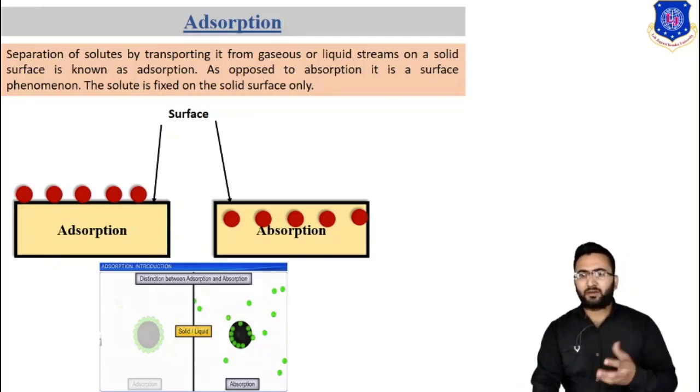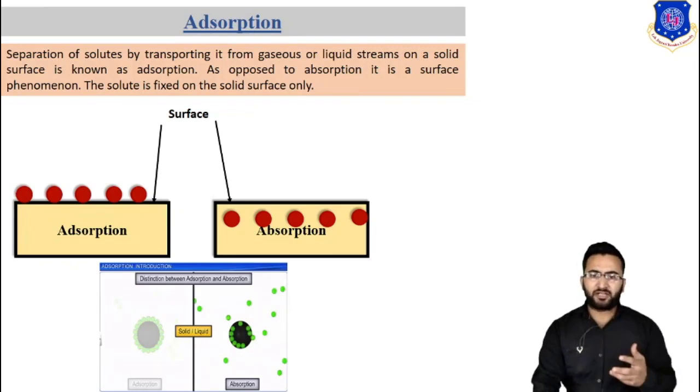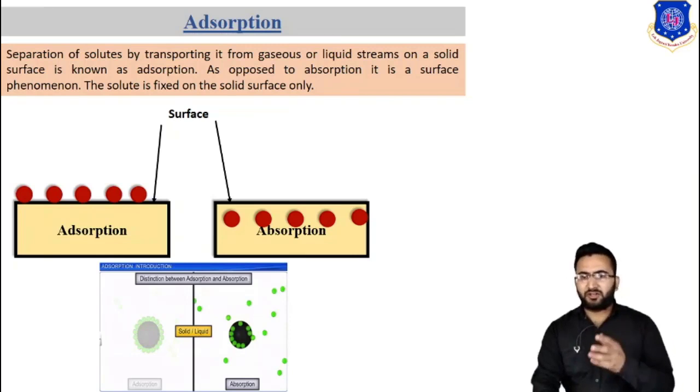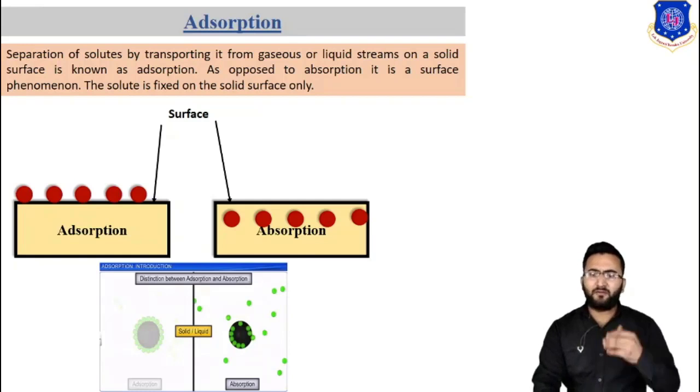After some time, the solid phase is completely saturated and transfer of species becomes extremely slow due to the lack of driving force. In such a case, the bed has to be replaced by new adsorbent, or the bed has to be regenerated by a suitable washing protocol. Removal of organics from an aqueous mixture using activated carbon is an example of adsorption.